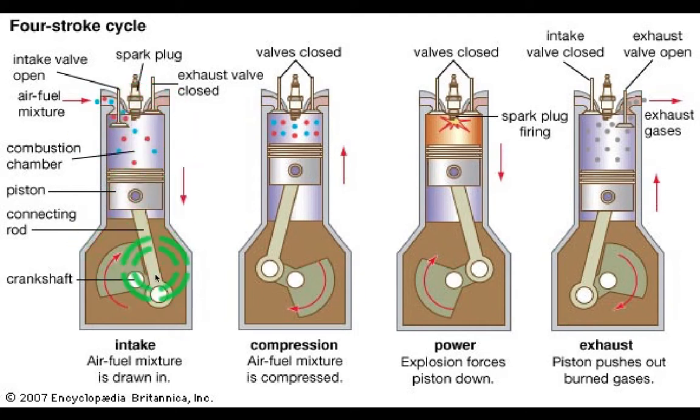Because this is like in a revolving, it's connected to the connecting rod, and connecting rod is connected to the crankshaft. And as you can see, the crankshaft, when it turns in a circular direction, this on the other hand goes in a reciprocating manner, in a perpendicular fashion, right? Up and down it goes. So when the crankshaft is going to revolve and reach almost here, that's the max it can go up to. That's how they've designed it, for it to reach its top.